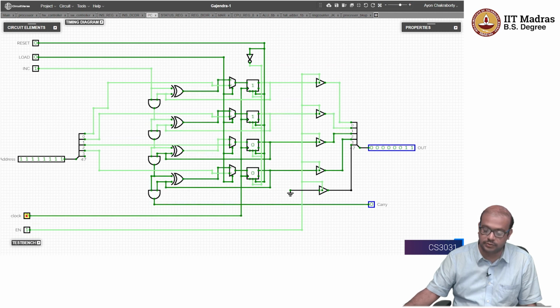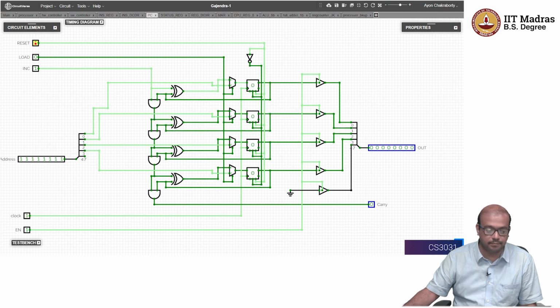it basically counts. Okay, so the other thing that also has to be looked at is the reset, right? If I push reset, it basically asynchronously resets the value of the counter. Okay, so this is a reset that I was using for the system reset. So if I click on reset, the program counter directly goes to 0.